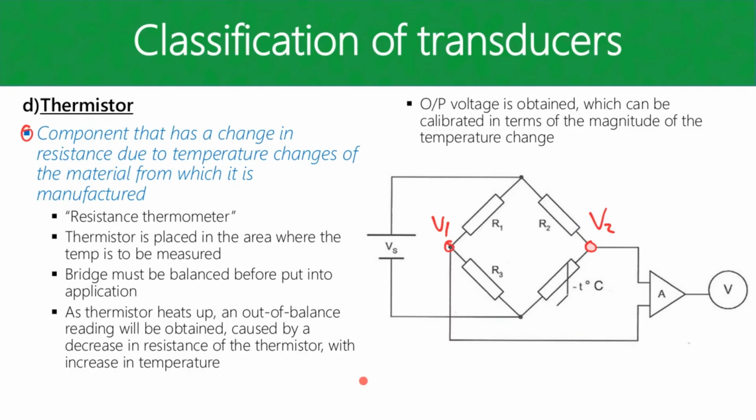Right, so then your bridge is balanced. And the easiest way to get the bridge balanced is just to have all these resistors equal in size to one another. You just get a bunch of resistors the same size as your thermistor at 25 degrees C, place them in, and consider your bridge balanced.